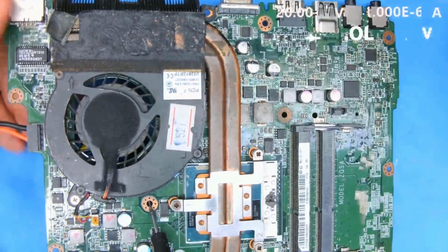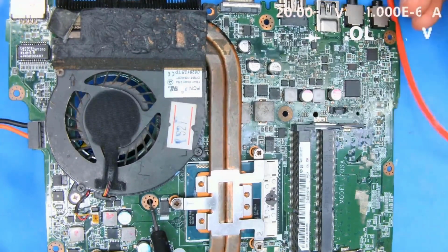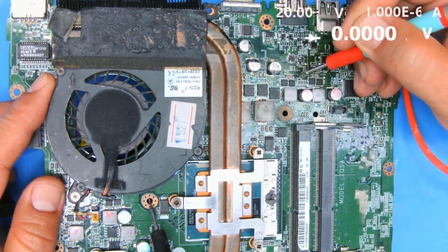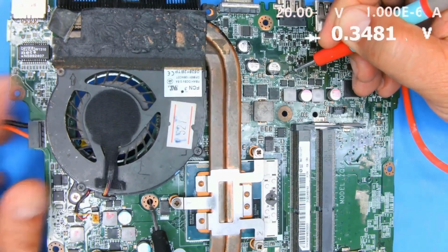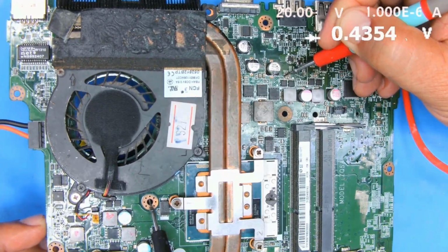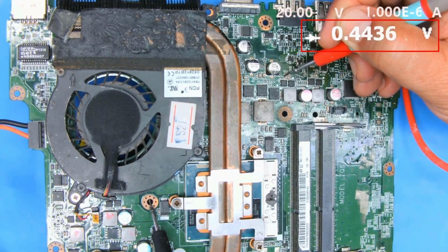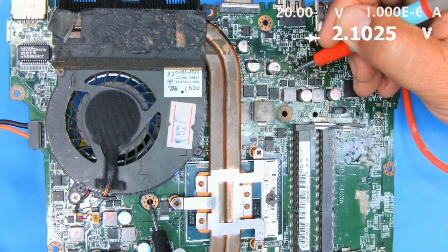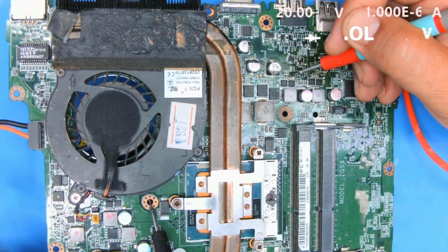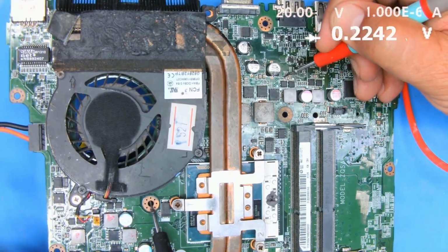So the method is to set the meter to diode mode. We measure at pin 49 using this side as ground. The 0.000 side here should not be chassis ground. It should show OL, over limit, but if it shows a diode value of about 0.4 volts, then we immediately know this is a high side MOSFET short. Because if the high voltage side shows OL or above 2 volts, that's fine. 2 or OL is okay. But if it shows a value starting with 0 point something, that's not right. If the high voltage side is shorted, it's 100% short. But in this case, it means it's a high side short.